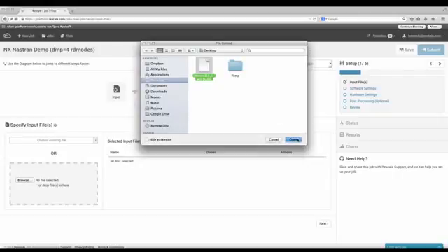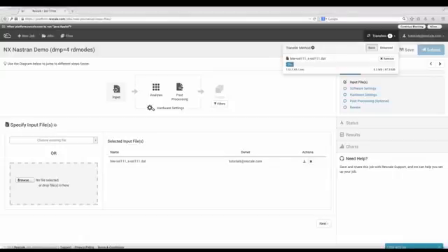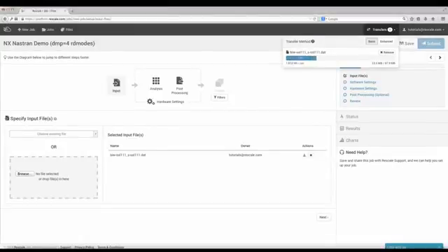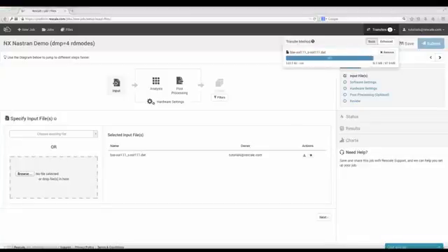In the top right, you can see the progress bar in the Transfer Methods section. Rescale has two different file transfer options. The basic option is a standard HTML transfer method, but Rescale also has an enhanced option that uses a built-in Java applet to perform multi-threaded file transfer and reduce the upload and download times.